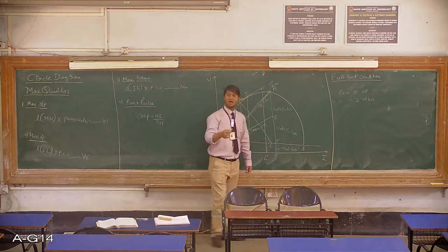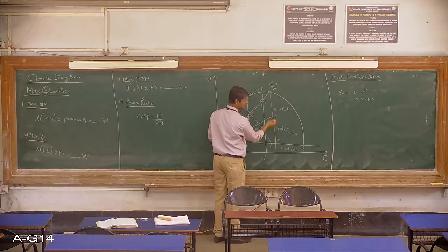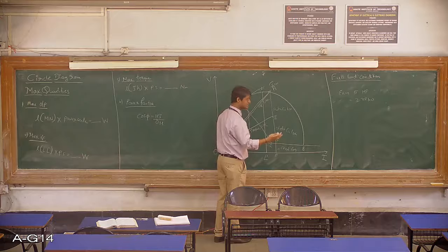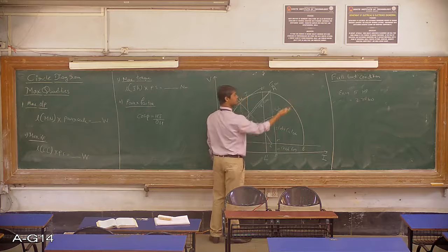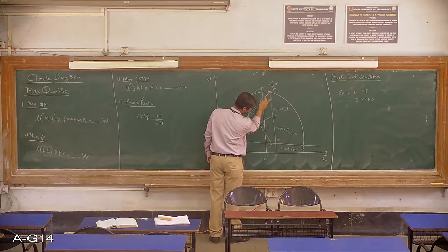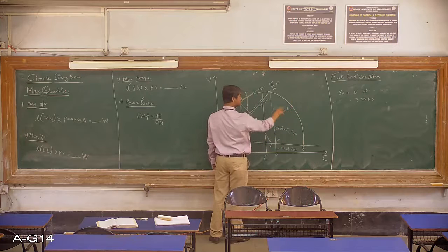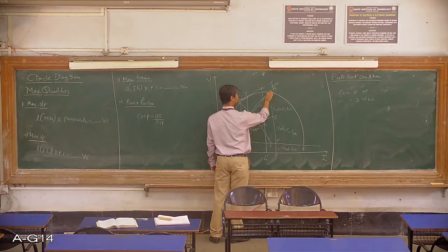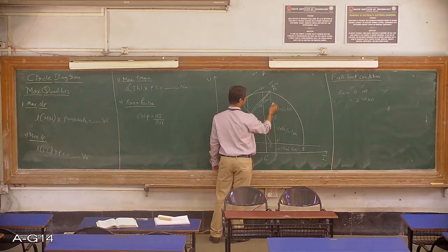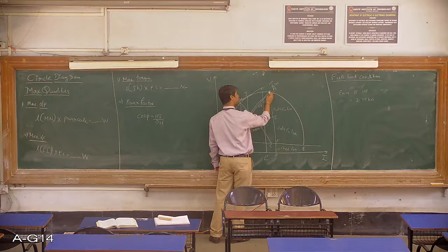That means after subtracting all the losses, the actual output, the machine is giving us 3.75 kilowatts output. But here from the point A, below all these parameters are losses. So adding that 3.75 kilowatts from the point A will get the actual output. But for that we have to extend the line from point A over its head.